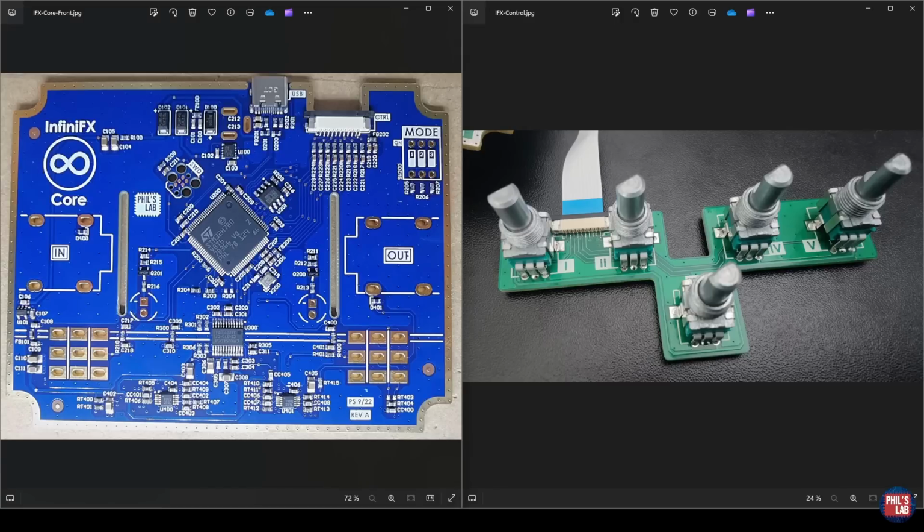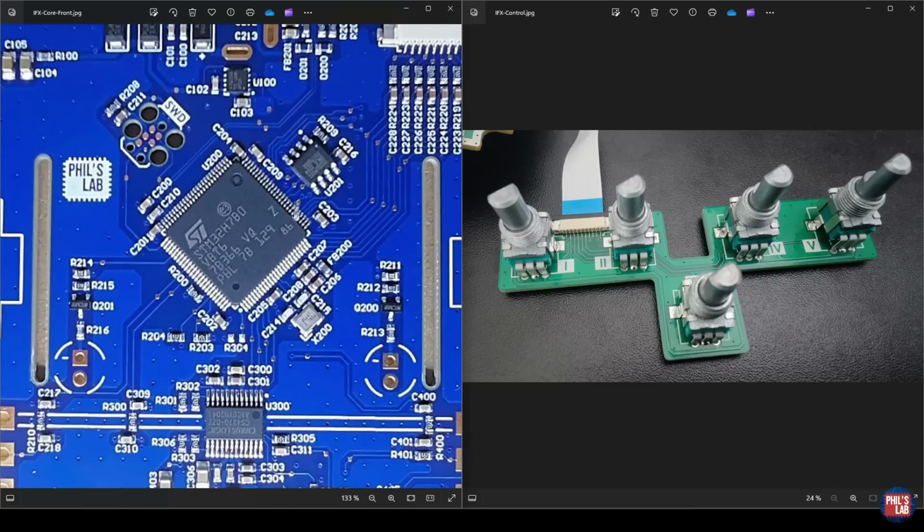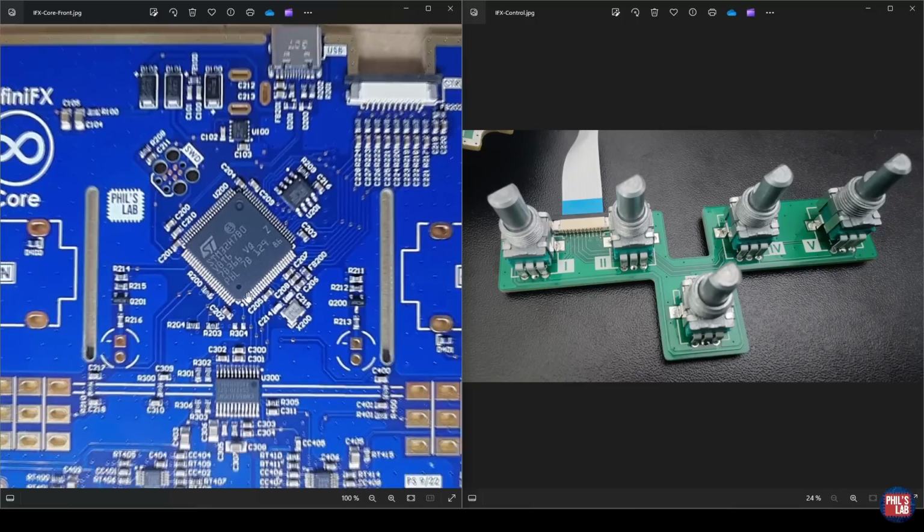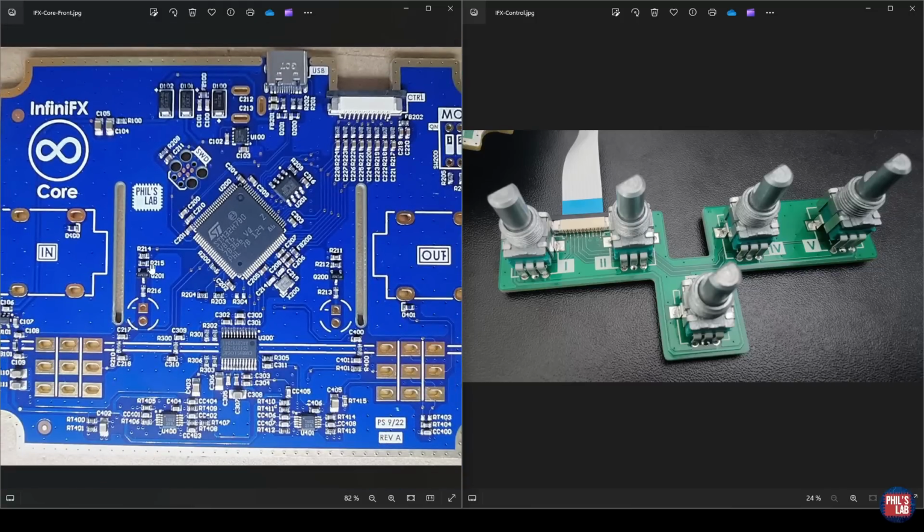The board we'll be running this on and writing software for, we can see here. On the left hand side we have the main board, so to speak, which is effectively an audio processing platform based on an STM32H7 microcontroller. This has various peripherals connected to it, ADCs, DACs, LEDs and so on, but also because we'd like to control this board, we want to change, for example, various filter settings, parameters of the effects that we're running on this